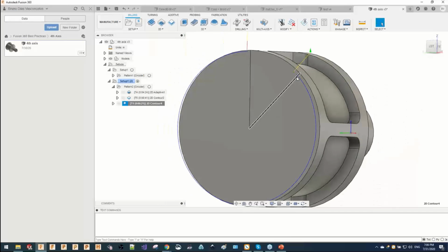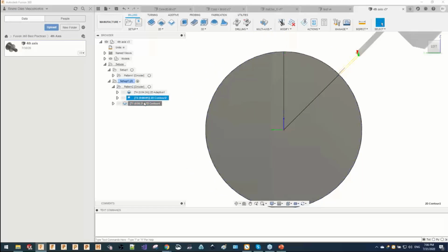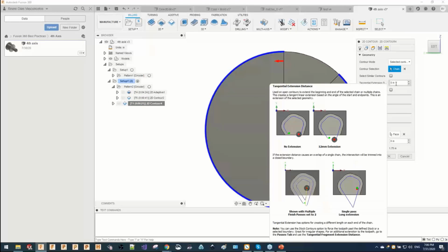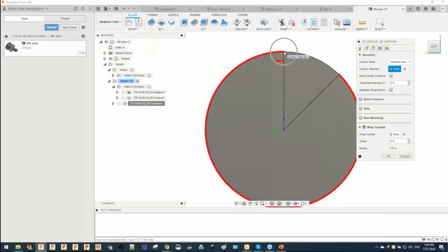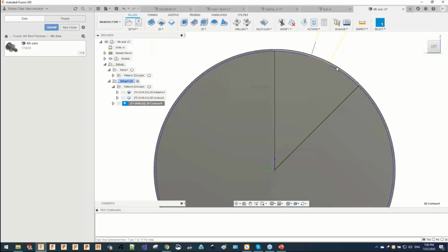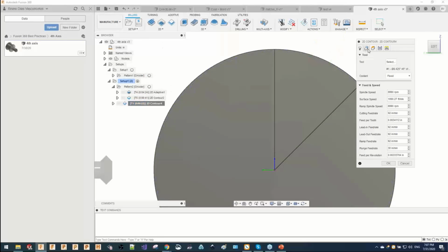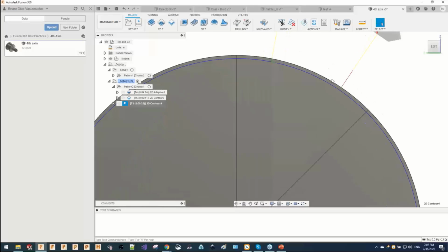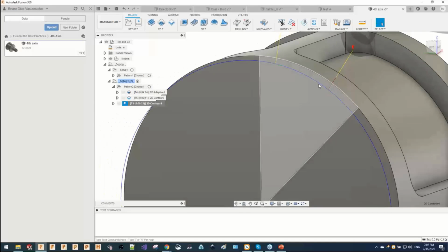But hey, Bruno, how can I continue the toolpath until I break the rest? Just go here and do tangential extension. Because what you're looking to do in short is extend tangentially this end and this end. So if you do here like 1 inch, let's do 1/2, so you can see it. Now I'm extending 1/2 inch both ways. So in short, if I do now 1 inch, maybe that should be enough. Yeah, that should be enough to break everything.